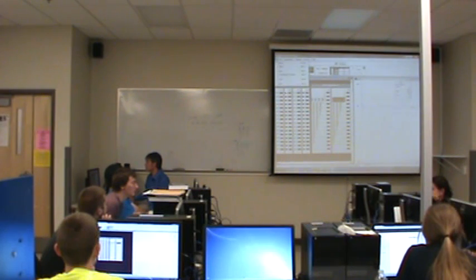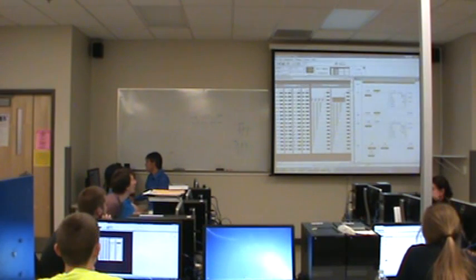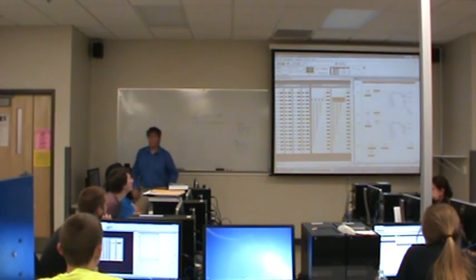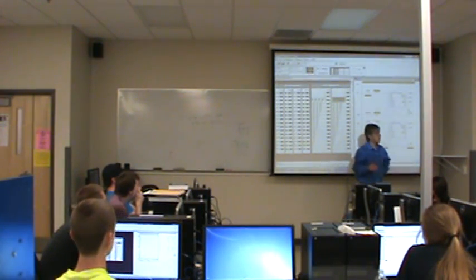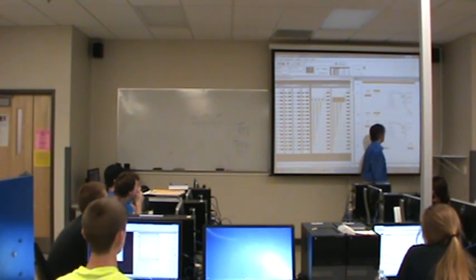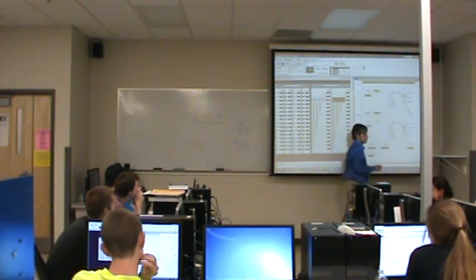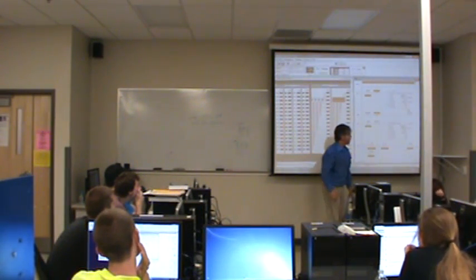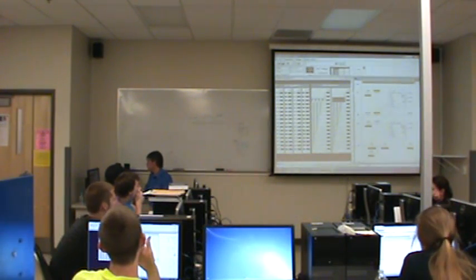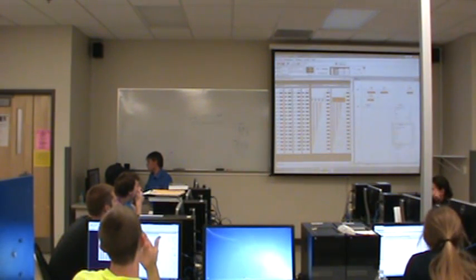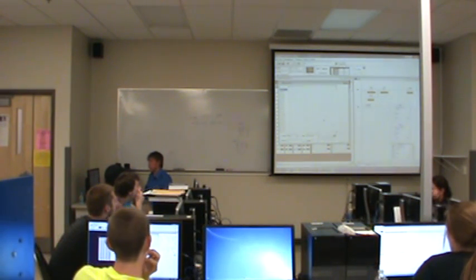Now let me go back and open up the other program. So your job is essentially pretty small if you use this program. All you have to decide is how many steps you want your sequence. You have to enter that here and here. And then you have to decide what input word and what output word you want it to work with. And then you have to decide what your list should look like. And then, ideally, you would put your lists into these move instructions rather than going in and manually entering the data in the binary file. If you don't want to do that, you don't have to.